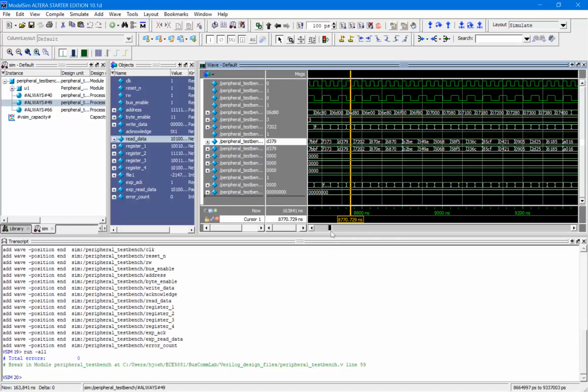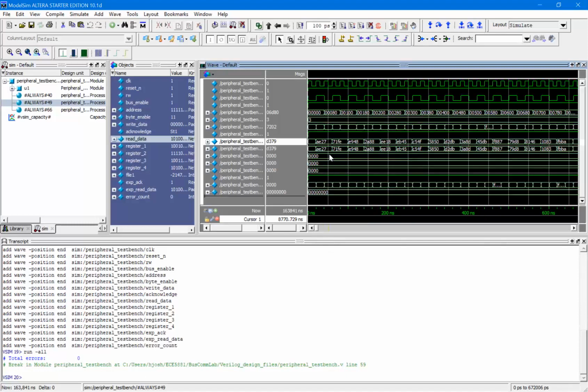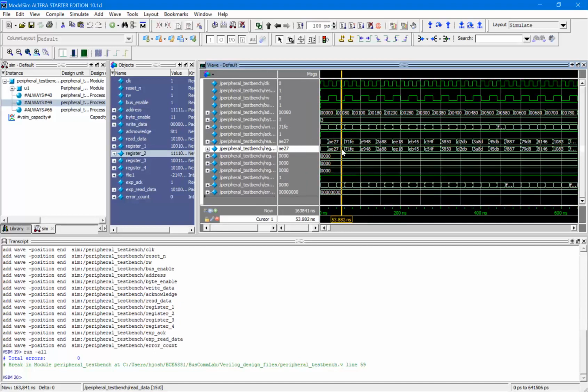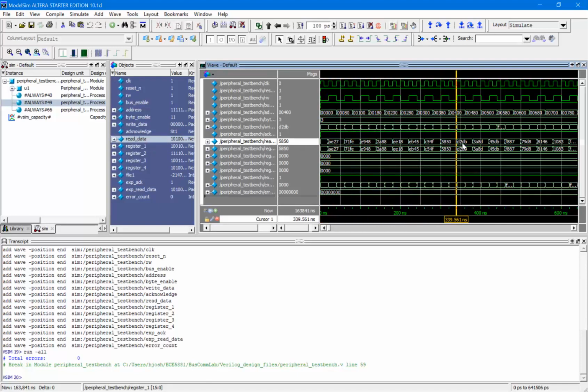Now, something else that a lot of people might have come across is red signals in some or most of their simulation. That could mean that you have some issues in your logic, but most of the time it meant that there were undefined signals from the beginning of the simulation. It wasn't given an initial value, and therefore it was undefined because it was never assigned to later on.